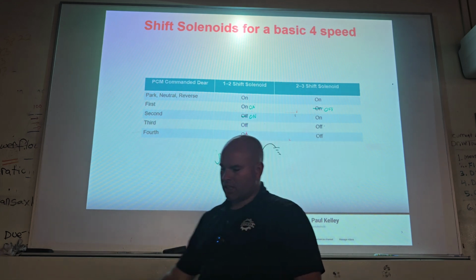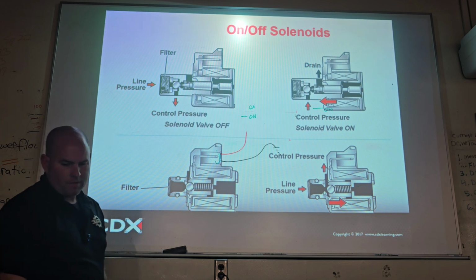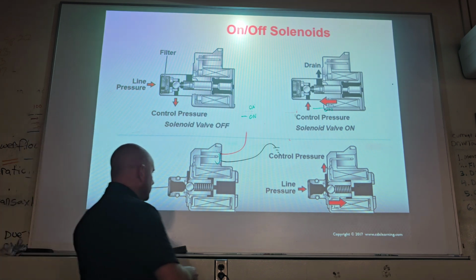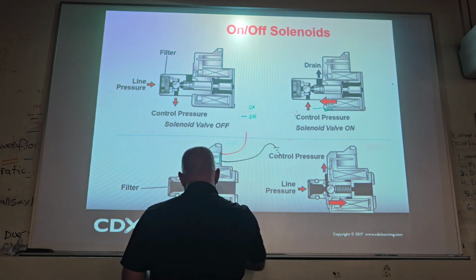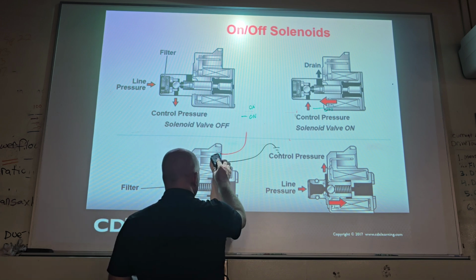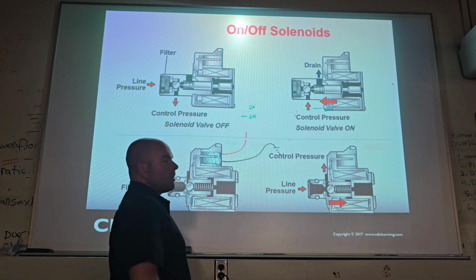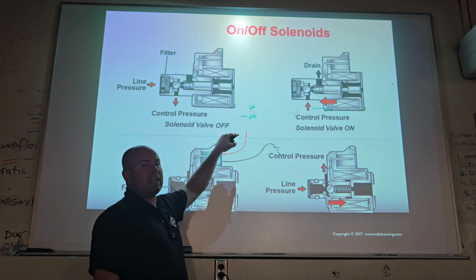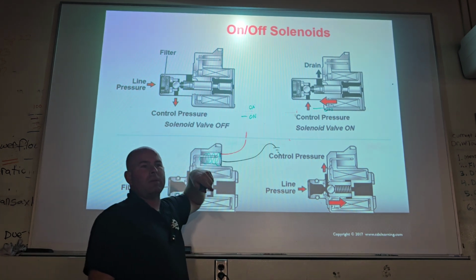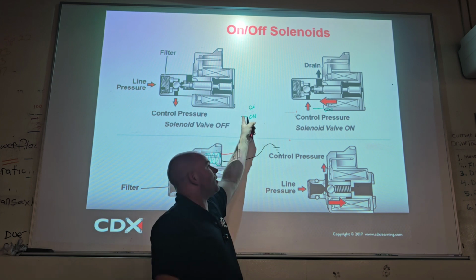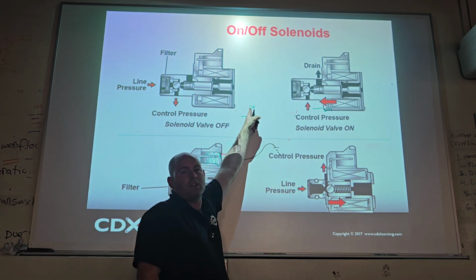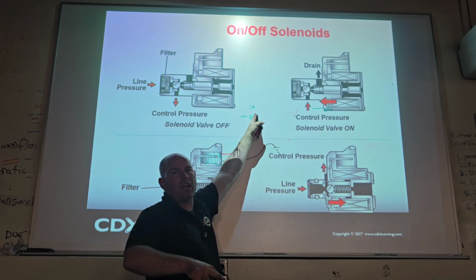that was easy because I was already in the valve body, okay? So if you are trying to do this, remember, we can measure at the valve body, but as you'll see as we get a little bit further, when it's a circuit code, that just means it's an open somewhere. An open here would do it, right? That harness could be inside the transmission, or it could be after the connector, and it could be going up towards the ECU, right? So it could have been a harness outside the vehicle.